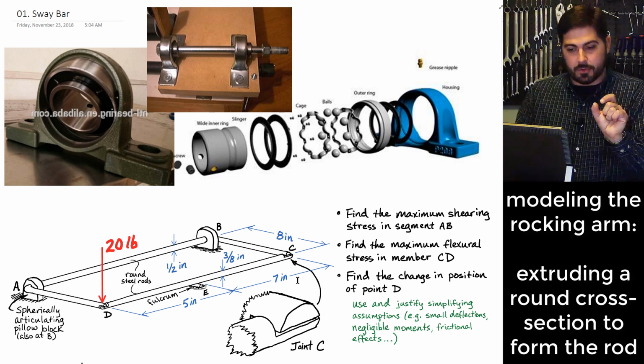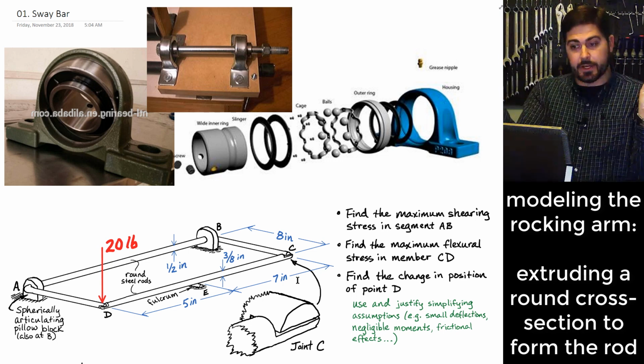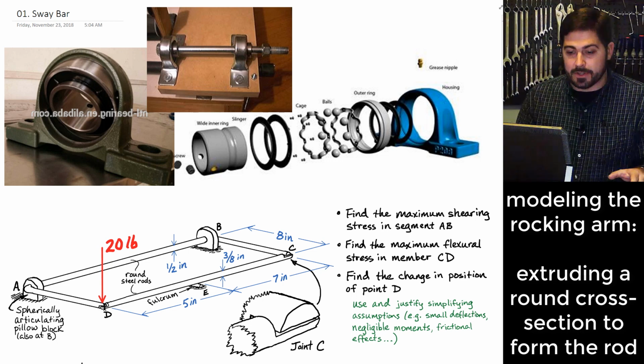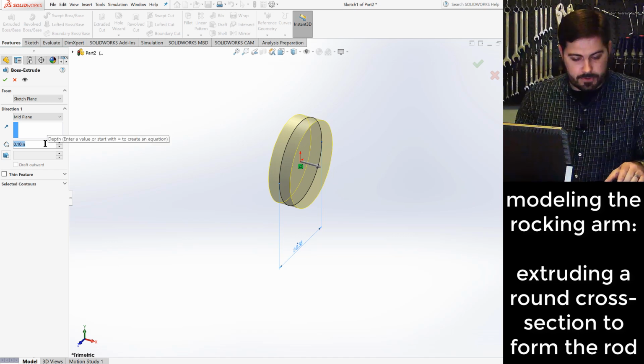That means I need essentially one radius on one end of rod AD and one radius on the other end of rod BC in order to extend that far, in addition to the 12-inch center to center distance. Okay, and so that basically means one diameter. So I basically add a 1/2 inch onto the original length of this, so I need it to be 12.5 inches. All right, so I go into my SolidWorks and I turn this into 12.5.